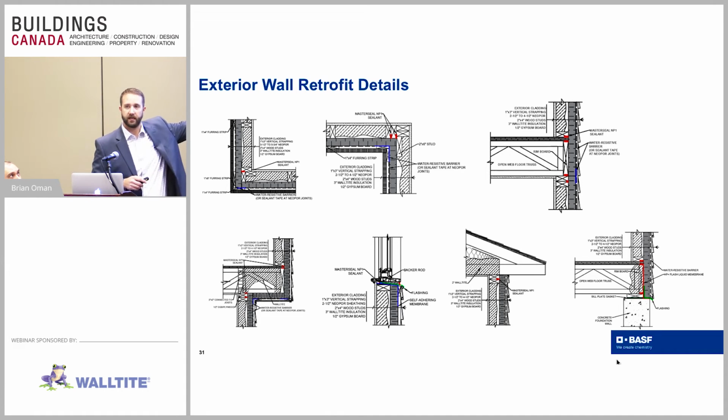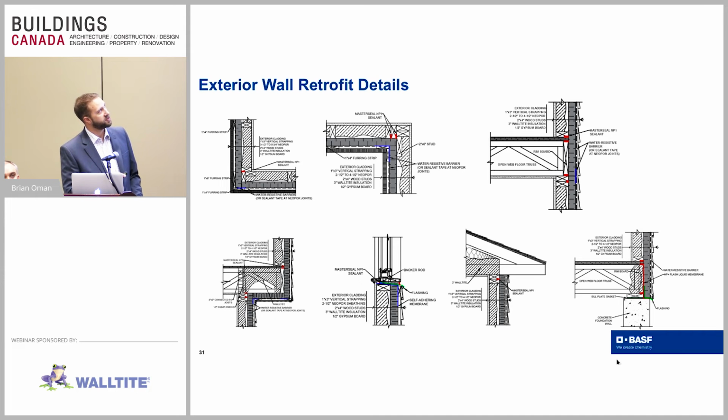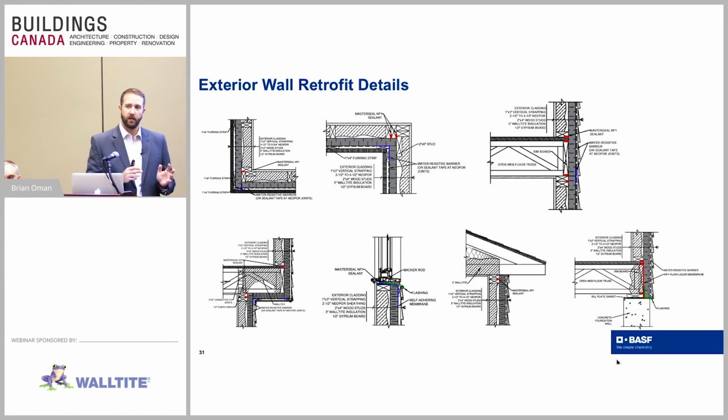As well as, say, in a cantilever situation or in your rim joist situations here, making sure that we have a continuous seal there. And especially with these sorts of situations, maybe in an existing home, we want to make sure we have a little bit of a belt and suspenders approach as well. So we're using the foam on the interior side for our insulation, our air barrier, and our vapor barrier, but we're also utilizing the sealant on the outside to hit those critical points of entry so that in case we do have a failure, maybe of one particular part of that system, we're going to have a backup to make sure that we don't have that air or moisture intrusion.